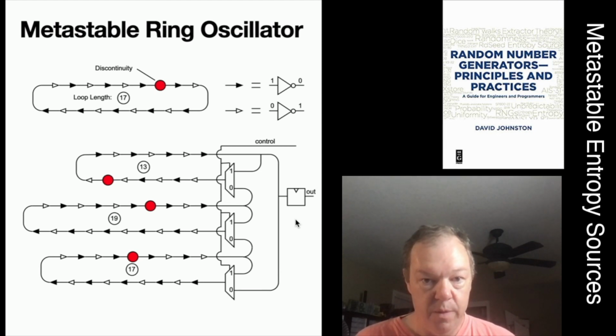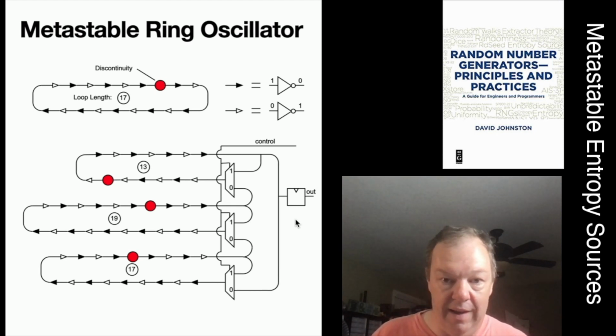But sooner or later, those discontinuities are going to bump into each other, because the noise is determining the time it takes to get from one side of a gate to the other. There's some fixed time plus a bit of noise, and what we know from these circuits is they collide very quickly. And that's partly because the activity in the circuit is creating some of the noise, so it's sort of depressing the speed of the one ahead and causing them to collide, through the power supply, and so they collide very quickly.